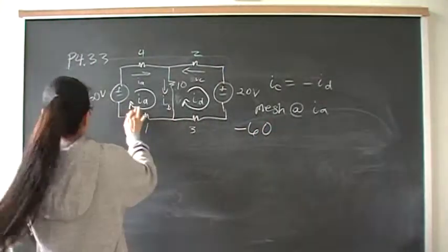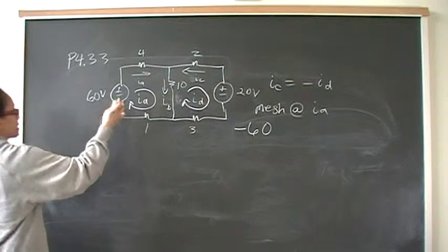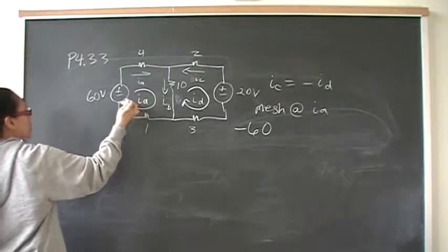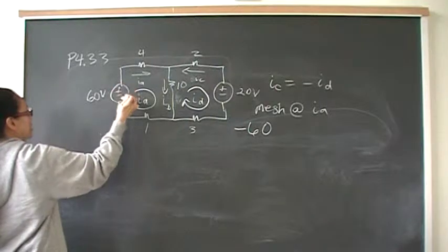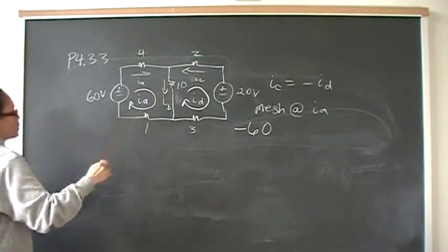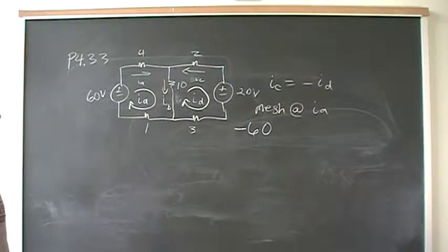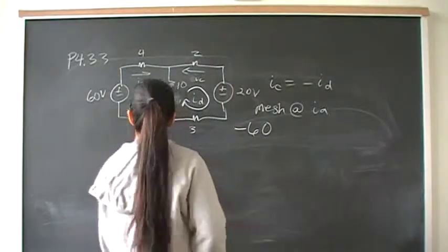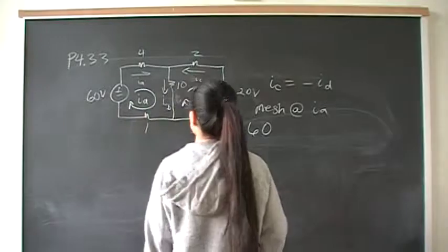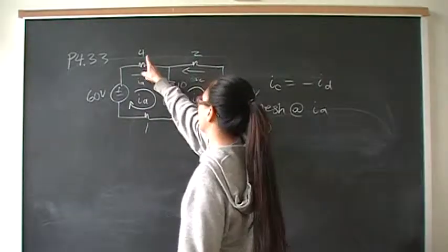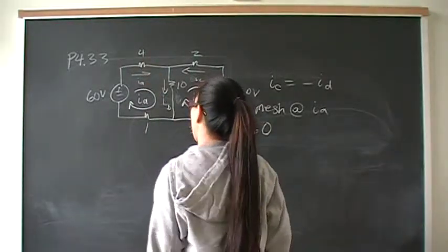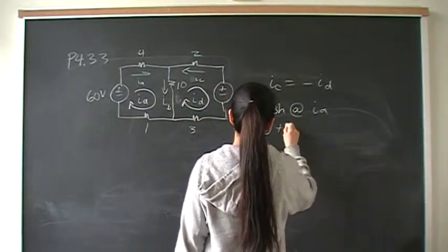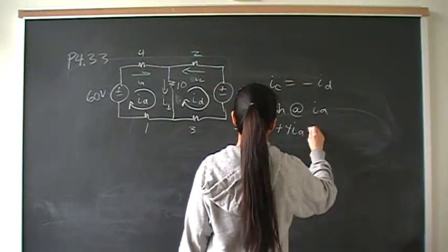So this is going to be important in part B, because then you're going to reverse the polarity, and instead of the first sign you're going to see being minus, because it's going to be minus plus, it's going to be plus. So your equation will start out with plus 60. In this case, we have a voltage drop with respect to ground, so the first sign that we see is a minus. Okay, so the voltage term here is going to be IR, right? So it's going to be IA times 4. So it's going to be plus 4 IA.